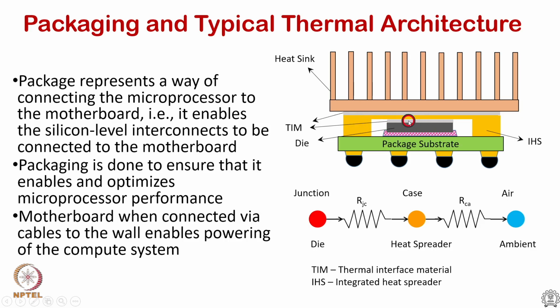However, the thermal contact between the device, the die and the spreader is usually very poor, because they are bare silicon and copper is typically used as spreader. So, to make sure there is a proper thermal contact, the thermal interface material, TIM, is used. So, this TIM connects the die to the spreader,